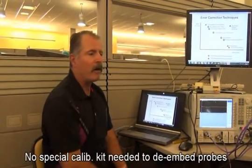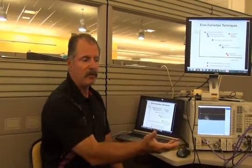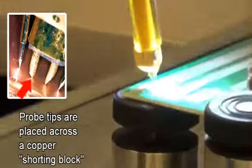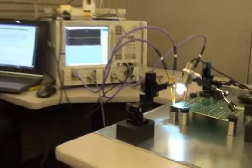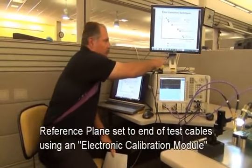With AFR, you don't need to build any special cal kit. All you need is to put an open or a short at the reference plane that you want. So for example, in our system here, we've got probes. We want the reference plane to be at the probe tip. So all we have to do is put a short or an open at the probe tip, and that's the calibration.